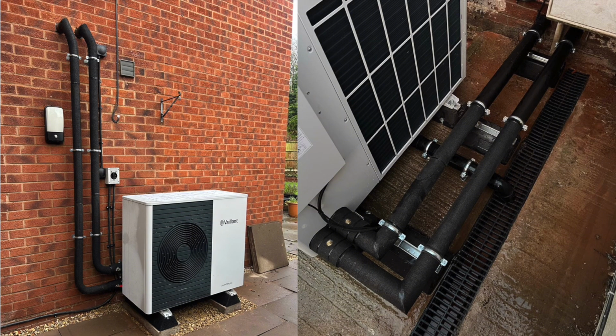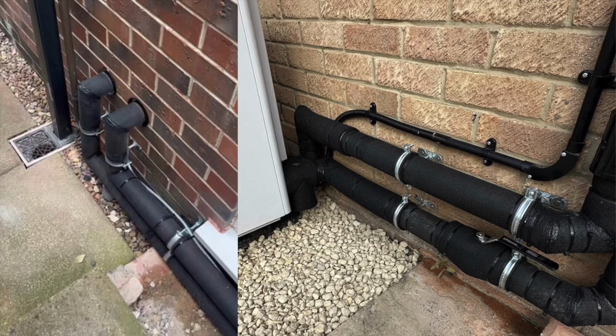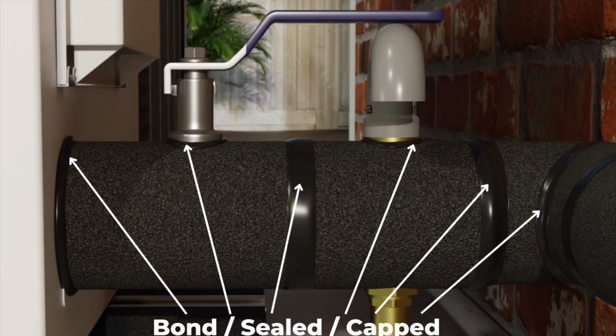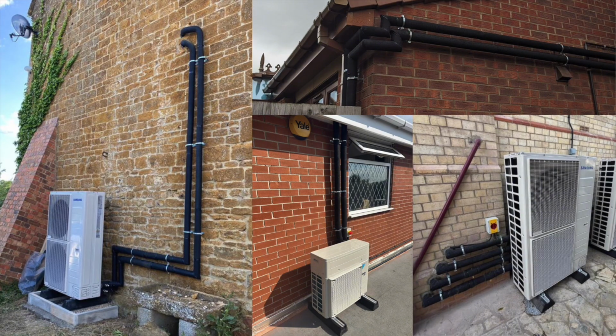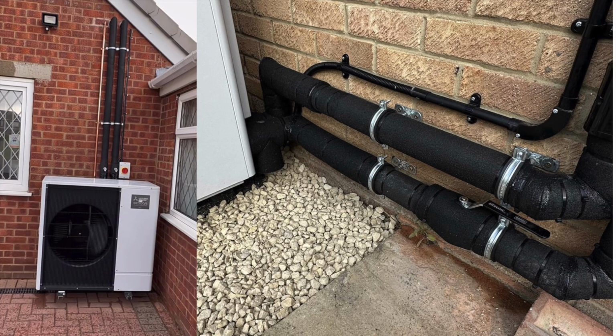and maintenance. So when we're fitting all the pipework, we're making it easy then to insulate every valve and all around and clip correctly. This is really important: to seal and cap everywhere on the insulation around all the holes where the antifreeze valves and lever valves are, and to the heat pump. And as you can see, these are just some photos that have been sent by installers, and how well it looks on a customer's house or property.